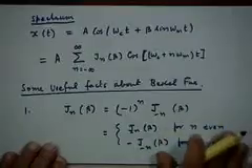At some points along the time axis, the signal was highly compressed where the instantaneous frequency was large, and at some other points the signal was much more sparse, and there the instantaneous frequency was smaller than omega c. The peak value of the instantaneous frequency deviation is equal to beta times Fm. So please remember that.